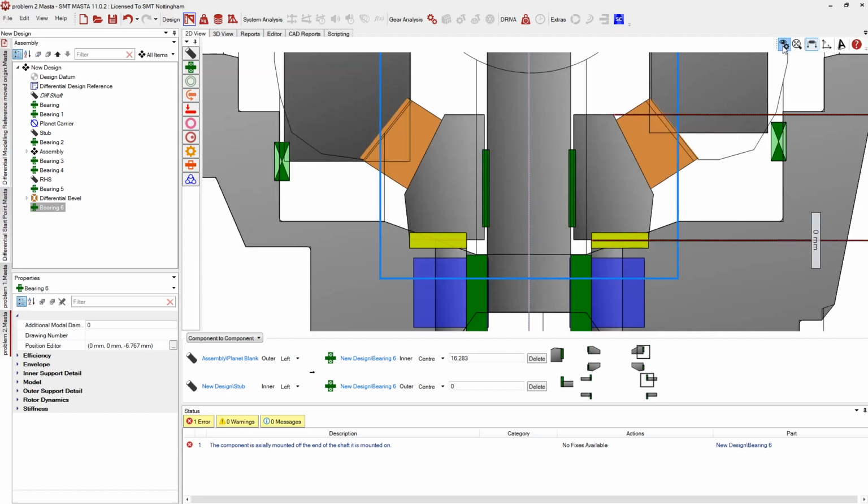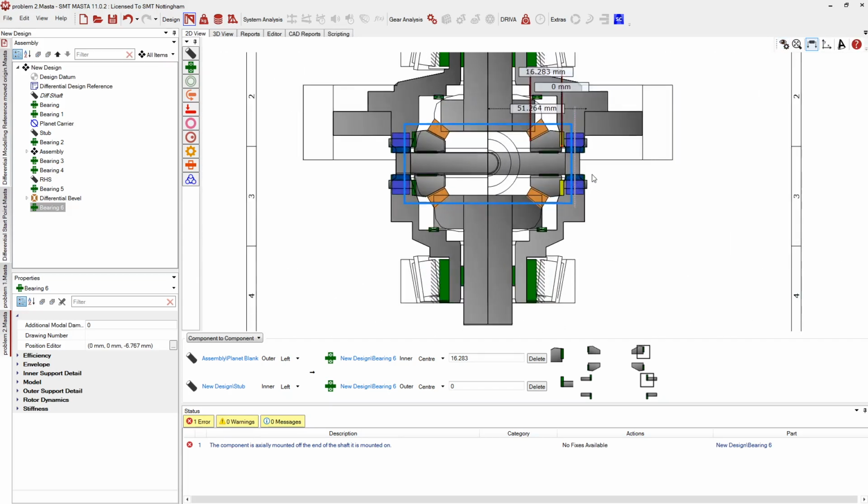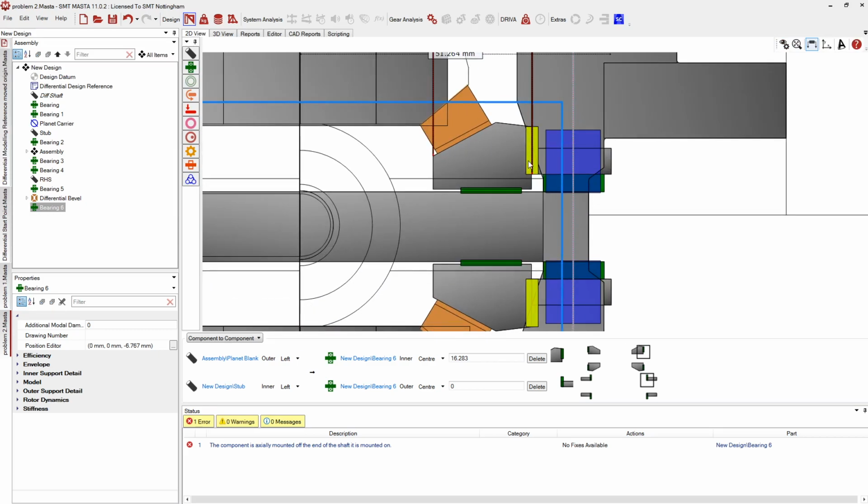And the reason it's doing this is because, again, it's an orientation thing. When you've got a concept bearing, which is what this is and what is often modeled by default for these systems, it's looking for a connection on the top and the bottom, when in reality this connection is looking from left to right.